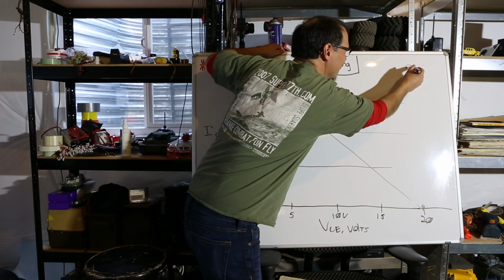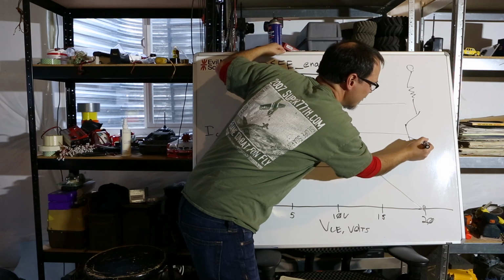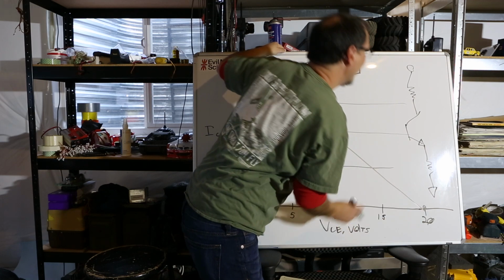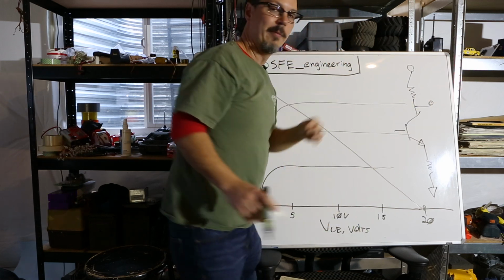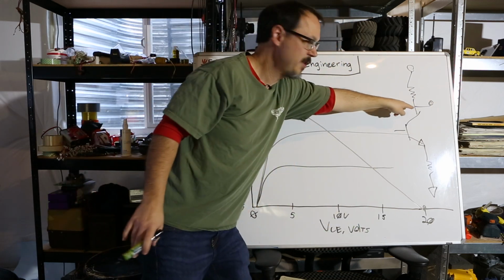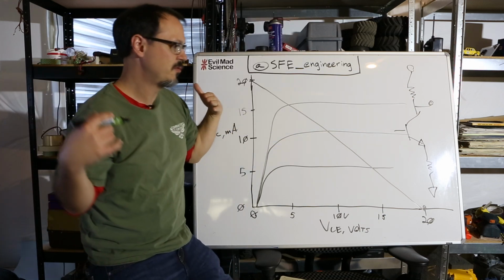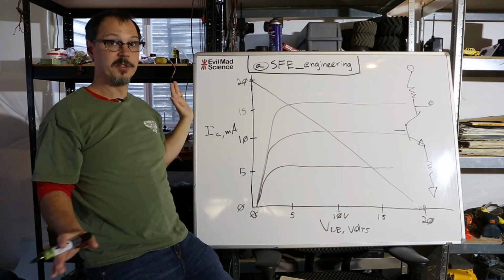The topology of the circuit is going to be, you're going to have a resistor, and a transistor, and it's an NPN, and then you got that guy, and that's going to go to ground, okay? And there's your base. And for a common emitter, this is where we take the output, okay? We want that point to be able to swing all the way up to the supply voltage and all the way down to zero, ideally.